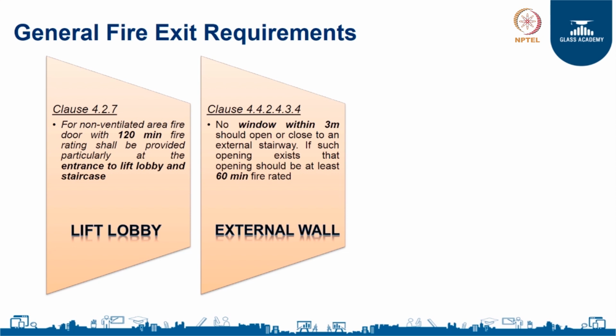So, now you see how people can arrive at what type of fire resistant material to be used, or what fire resistant system we need to use. The document clearly states that for a lift lobby application one needs to use a 120-minute fire rated system. Again, we need to emphasize that fire resistant glass is never used on its own. It is always a part of a system.